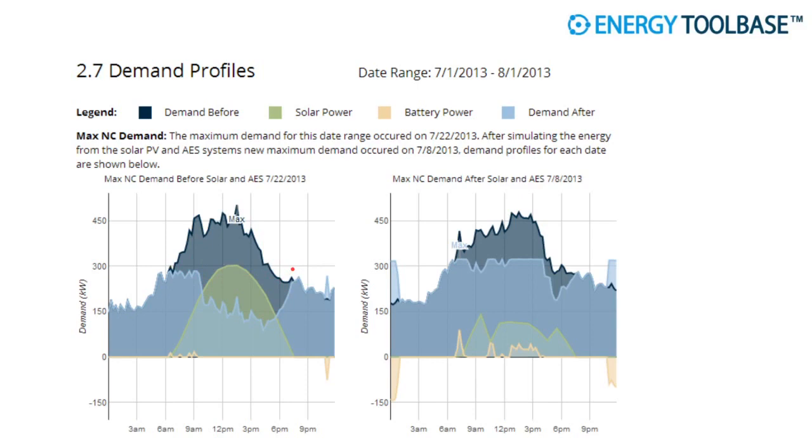Demand electricity is expensive, but most solar installers who have looked at commercial solar know that the true demand savings for this day don't matter if the very next day you have a partly cloudy day, and the solar array turns off because that one cloud in the sky has inconveniently located itself on top of your array. If that's the case, there's no demand savings for the entire month, because demand savings are calculated not on a day-to-day basis, but on the maximum 15-minute period of peak demand, and that can comprise, in some cases, 70% of a commercial electric bill, and sometimes more. It can get real extreme.